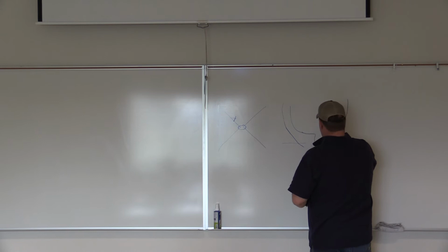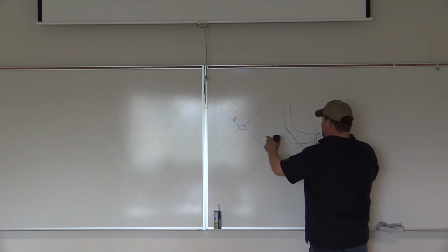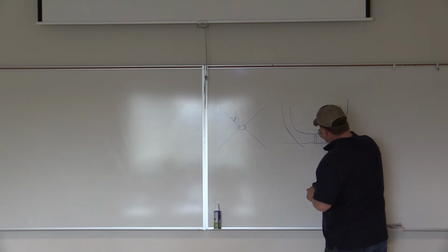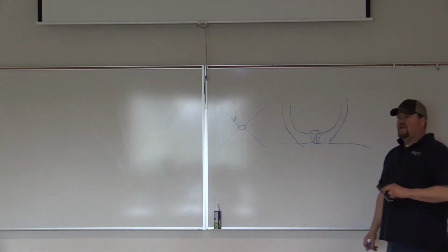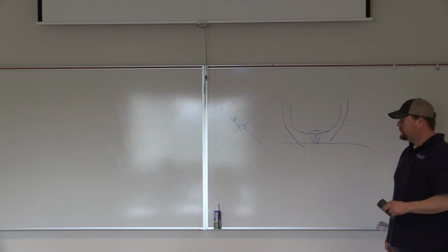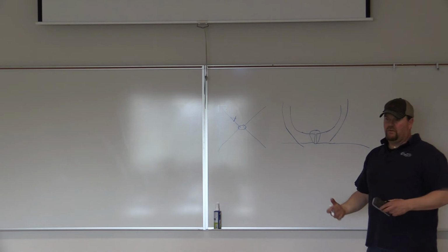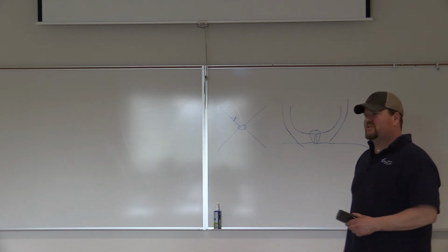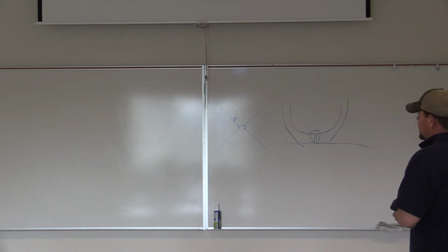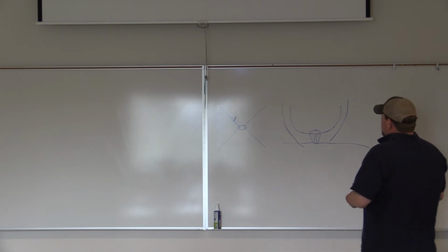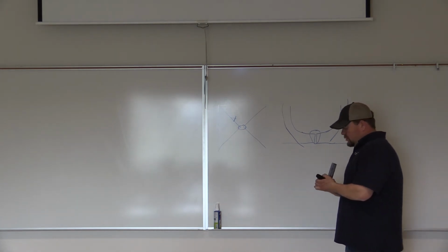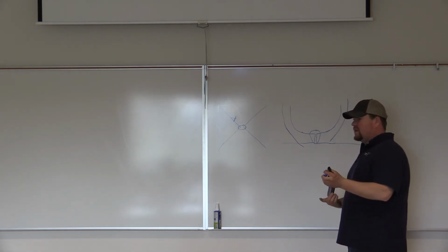So this one you'd see a lot with flux core as well, okay. And your first root weld is supposed to look like that. Consume that all the way without any prep. And then from there you can fill the rest of the way out, which the flux core works pretty good because this stuff's pretty smooth. Right? Quick. It is quick. Did that help answer that? Yeah. Okay.